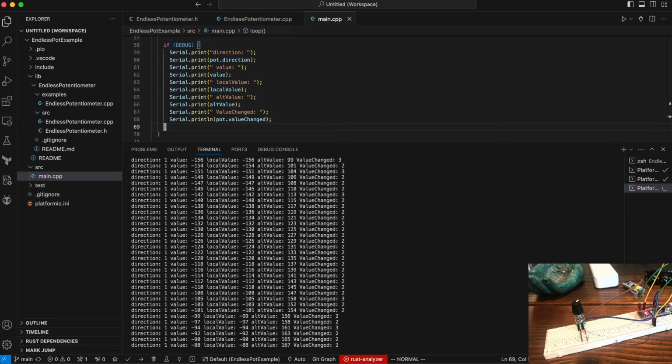Before I end today's little session though, I wanted to also talk about why would we use one of these when we can use an encoder? Well, there's advantages and disadvantages to both of them. Potentiometers provide a continuous analog output, right? If you have a need to provide a very smooth, continuous response on your circuit, then a potentiometer makes more sense.